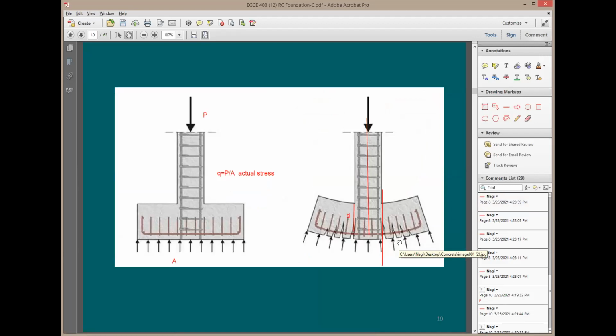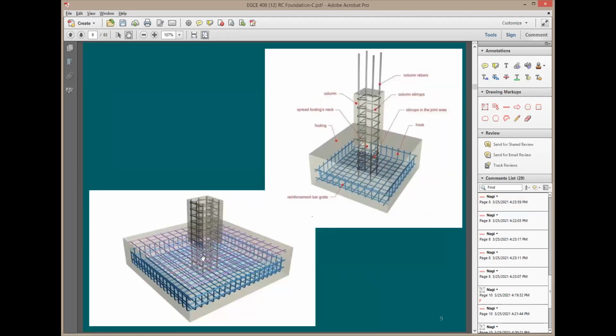Okay, I guess now I have a feeling for what this pressure is going to be doing to my footing, and the reason that I have the bottom rebars and not the top rebars to be used. Now the question is, why would you need any top reinforcement here? Sometimes this top reinforcing is helpful during construction because you'd like to brace this column rebars while you are putting the concrete. So you're going to put some rebars here on the top anyways. And these rebars can count when it comes to the minimum reinforcing ratio. Also, just in case you need the help of this compression steel, you can use it if you want to. But mainly, it is done for construction.